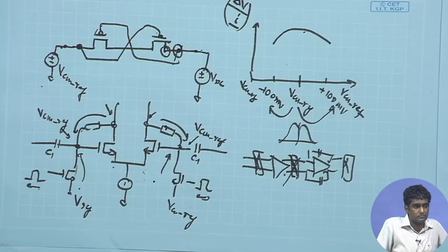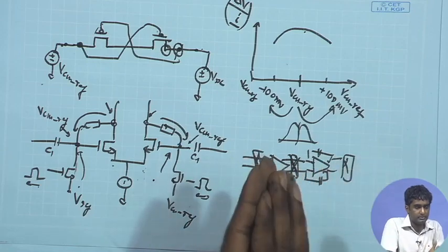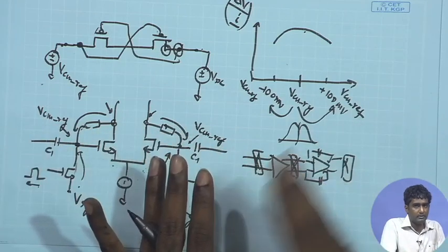But this simulator solves by using some mathematical equation. So why will it take 1 second or something like that? It's not a mathematical simulation. If you are using time domain simulation, it is basically solving matrices at every time step. Just like you do KCL, KVL, at every time step it will be solving KCL, KVL, finding out the next DC condition for each circuit point, each node, and then again finding out the small signal resistance values and the capacitance values at every point, and again solving the KCL, KVL at the next time step. So in the transient simulation it is something like a matrix simulation.